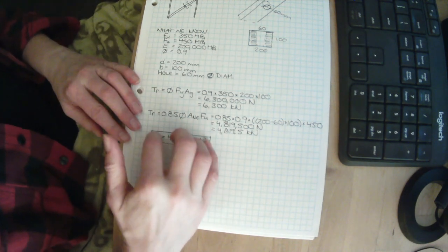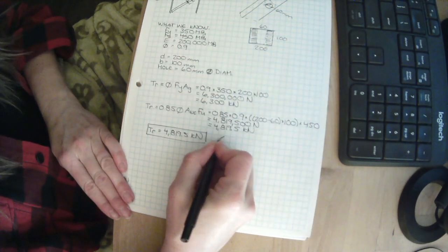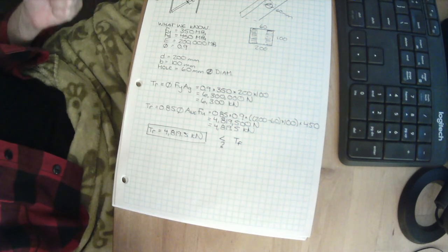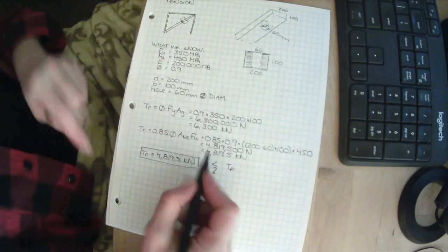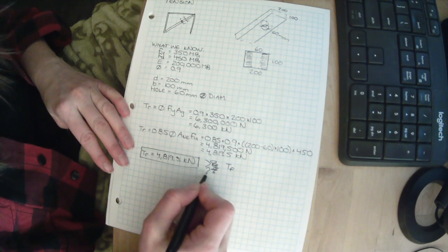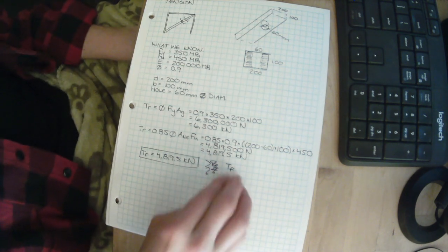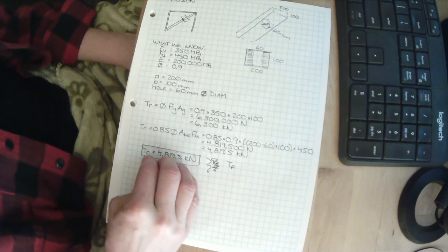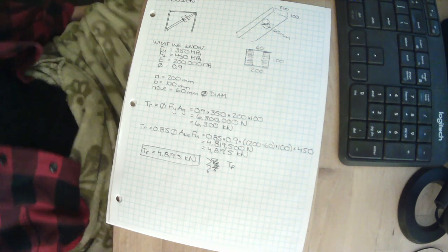I would often even embed elements, because now what we would want to do is ask: is this less than some TF? We don't know what the load on this was, so that wasn't a relevant question this time. But remember, we want to make sure TR is greater than TF. So we would find some factored load on this, and then we would want to make sure the capacity is greater than the factored load. The reduced capacity is greater than the factored load.